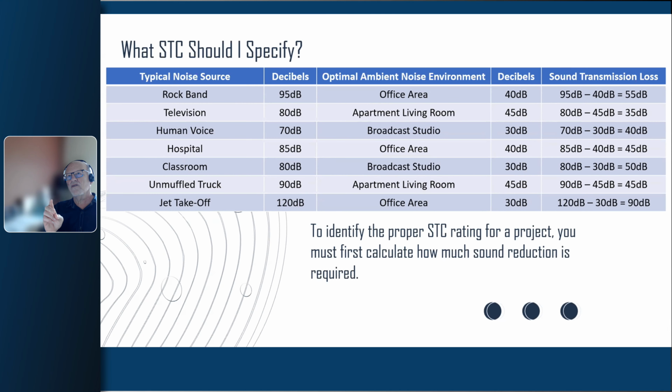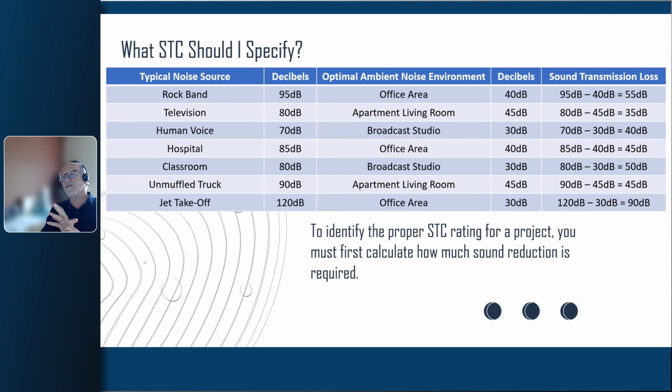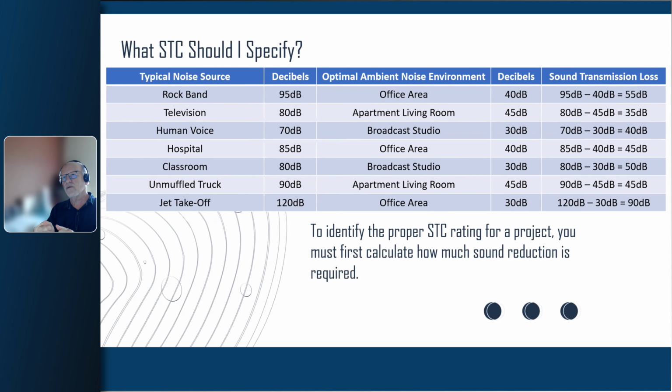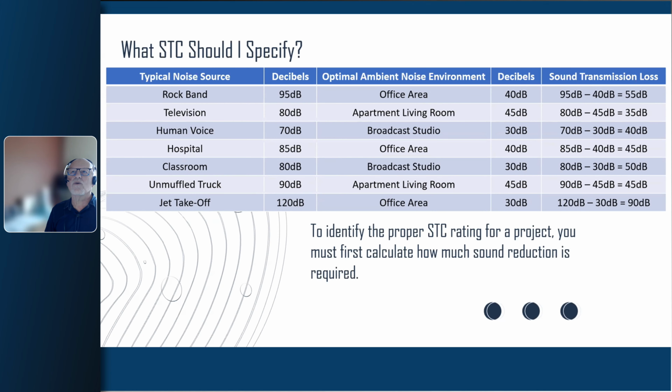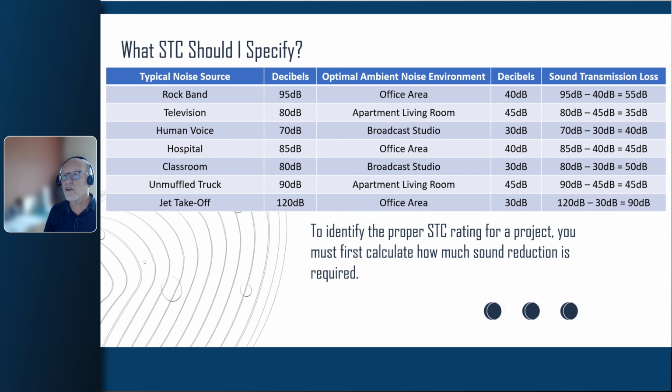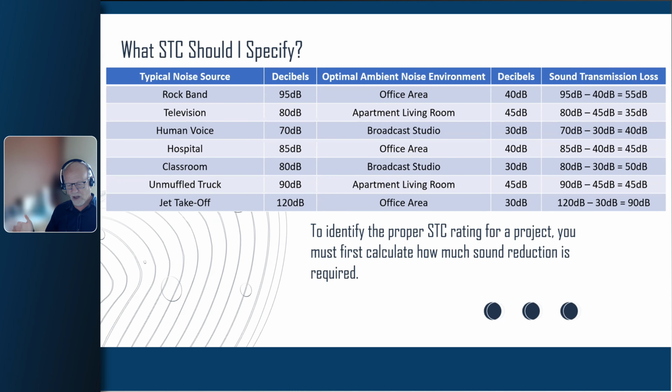So we decided we would turn around the sound test and create noise in the exhibition hall, obviously a huge room, into a small area like the stairwell. And we found that the results were 4 or 5 decibel STC ratings lower using the exact same equipment and with the doors, everything was exactly, nothing was changed.